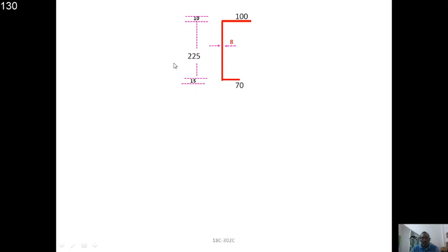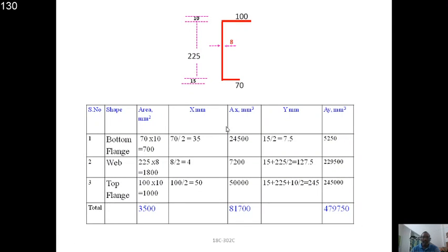So using these dimensions, now we are going to calculate the ax and ay products. Follow the same instructions. Always see where the origin is. So calculate everything from the origin. So this is the point of origin. Keeping in mind that while calculating the x1, x2, x3 values and y1, y2, y3 values, always take the dimensions from the origin only.